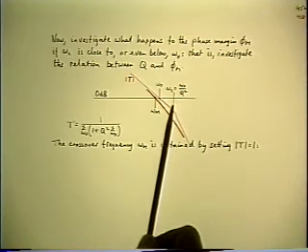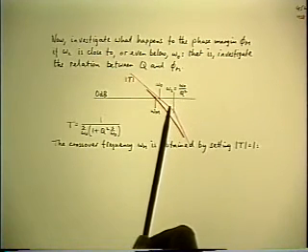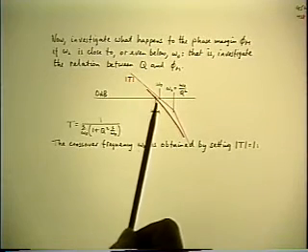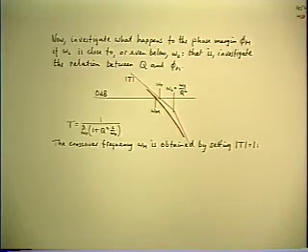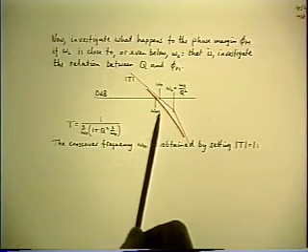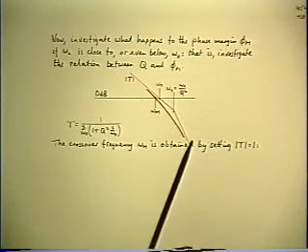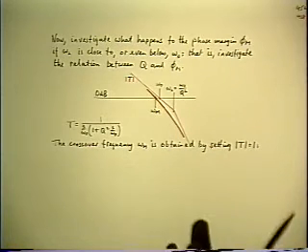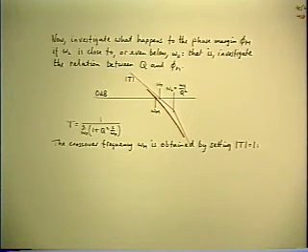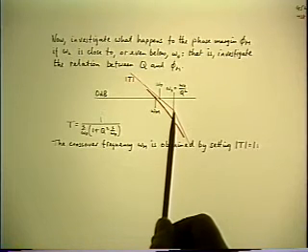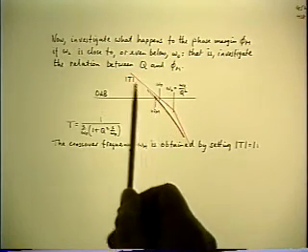The phase margin is defined in terms of the phase lag of the loop gain at the crossover frequency. Now, this is one of the rare cases where you actually have to account for the smooth curve at the corner, and the asymptote itself is not sufficient. The reason being that we want to allow omega 2 to move through omega 0.